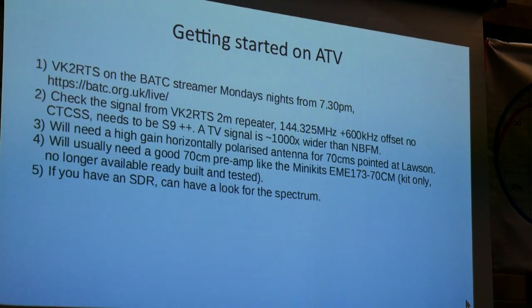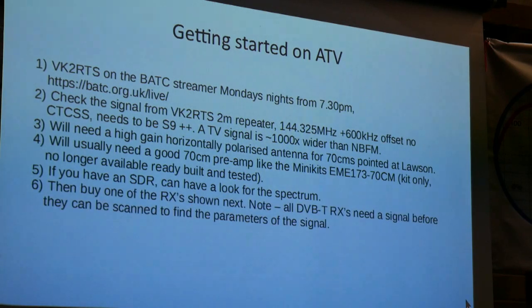With an SDR, it's really handy having this, because you can have a look at the spectrum, and you'll be able to see the spectrum before your set-top box or your dongle or whatever it is can decode it, because it's going to have to be 5 or 6 dB above the noise before you'll be able to decode a signal, but you can see it on the SDR. So then you can say, oh right, I've got something here, I just need a bit more antenna gain, higher, whatever, and you might see if you've got a chance then.